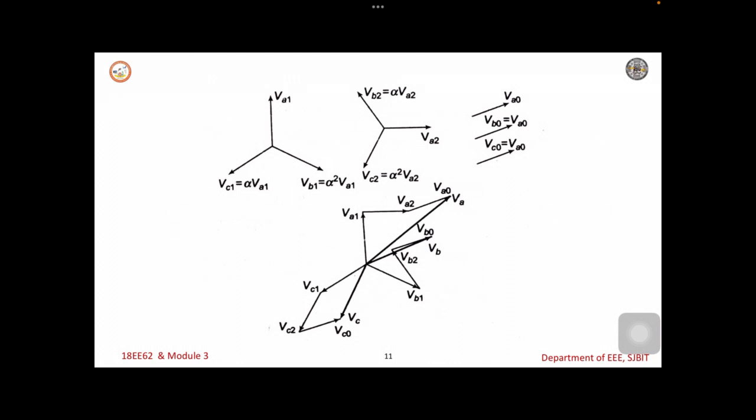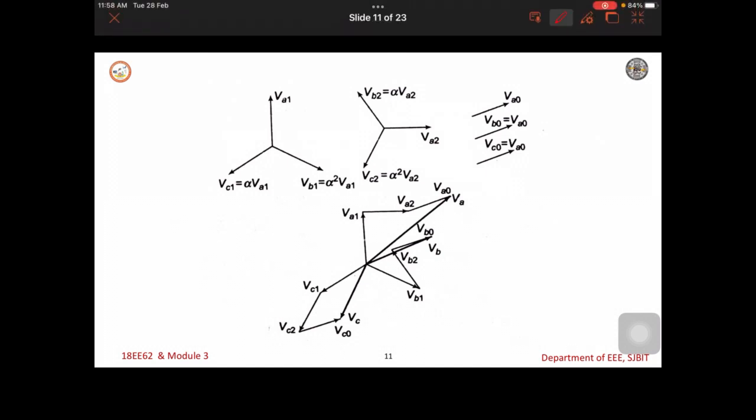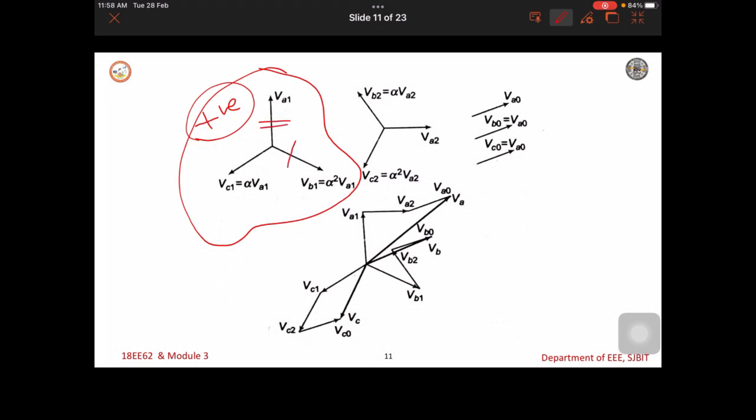This you can see in this sketch. Here we have the positive sequence component. Here we have 3 phasors. All these 3 phasors are equal in magnitude. They are phase spread by 120 degrees. They have the sequence same as that of the original phasor. That is, ABC is the phase sequence. Here we are measuring the angles in the anticlockwise direction, and naming will be in clockwise direction.